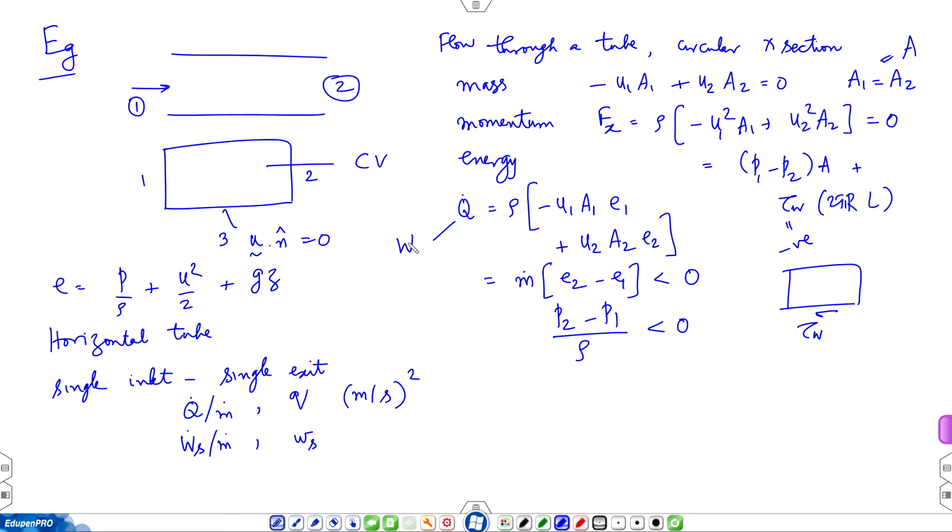So, you can think of total energy as mechanical plus thermal. So, thermal is constant, and this mechanical part is diminishing in the flow direction. So, from that angle, this q dot is referred to as a loss, energy loss. You should not say energy is lost and the conservation of energy principle is violated. It is not, because it is getting converted to thermal, but the mechanical part of it is lost in the flow direction.